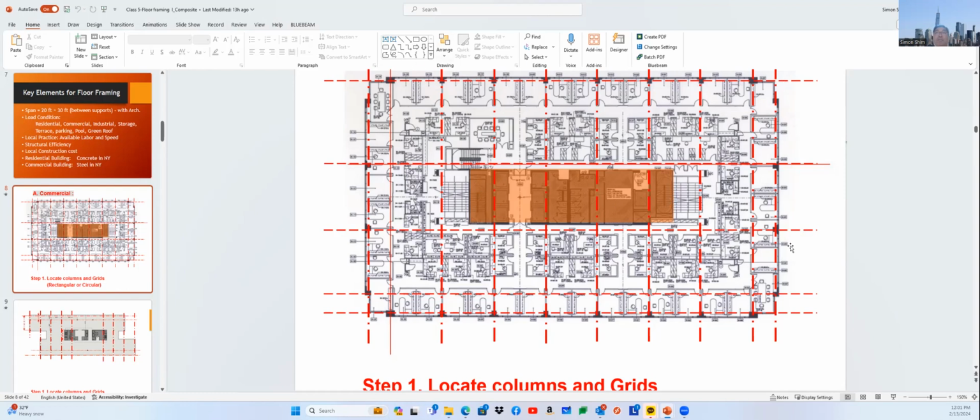If this building is much bigger, obviously you need more. But typically in a high-rise building, you're limited in your site area, there is a total gross floor area requirement, and owners maybe want a tall building. There are many factors you need to meet. I think you end up with a decent size, big floor plate, which is usually covered by 2 elevators in a typical case.